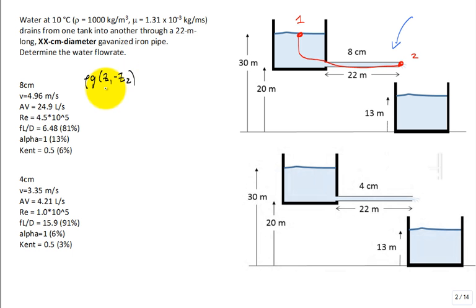That's the pressure due to the hydrostatic pressure that drives the flow through the pipe and discharges it. If it didn't have any gravity, you wouldn't have any flow through it, right? Okay, rho g delta z. Then that goes to kicking it out with a certain kinetic energy, 1/2 rho V exit squared,